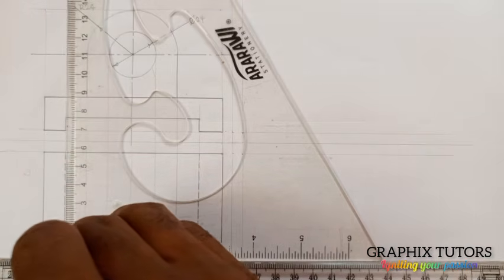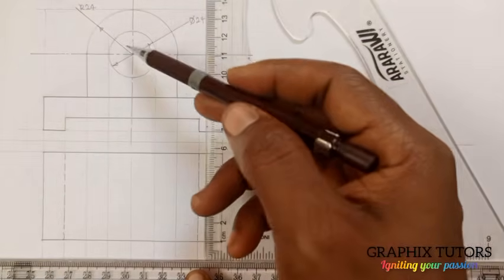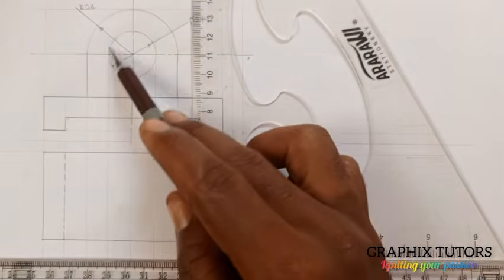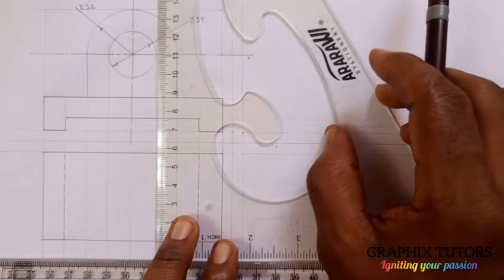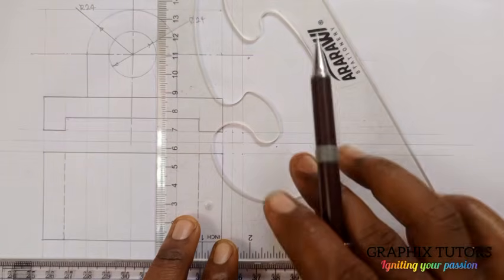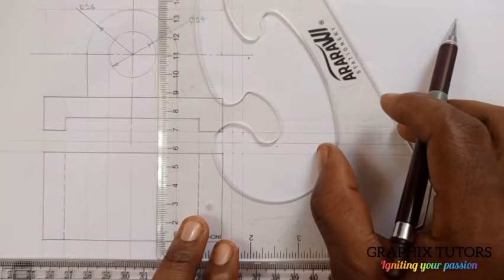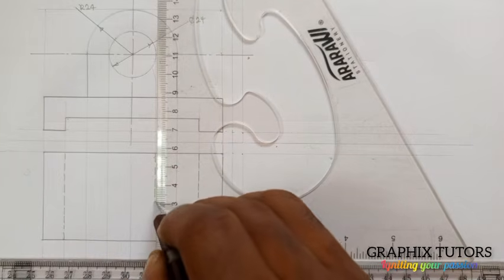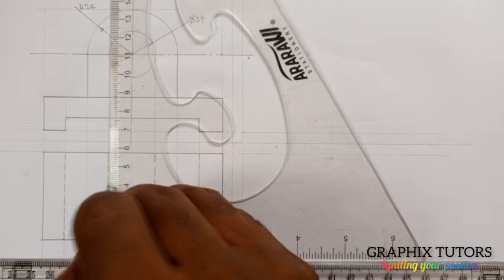This is what we have here. Now, from here, it shows that if you're looking at it from the top, there's a hole in this circle, right? So you cannot see it. To show it on my plan, I told you when you're looking at the plan perpendicularly, you see any circular object as a straight line. So on the plan, the circular object will be in the form of a straight line. So I'm going to show my hidden line here. Then I'll come here also and show my hidden line here.